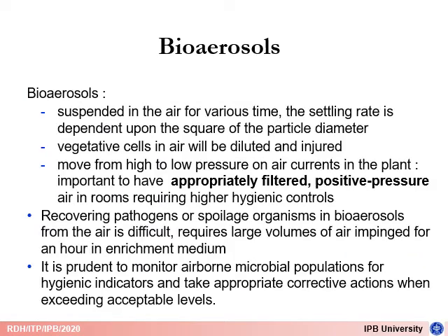Bioaerosols are suspended in the air for various times, and the settling rate depends on the square of the particle diameter. The vegetative cells in the air will be diluted and usually are injured. They move from high to low pressure on air currents in the plant. Therefore, it's important to have appropriately filtered positive pressure air in the rooms that require higher hygienic controls.